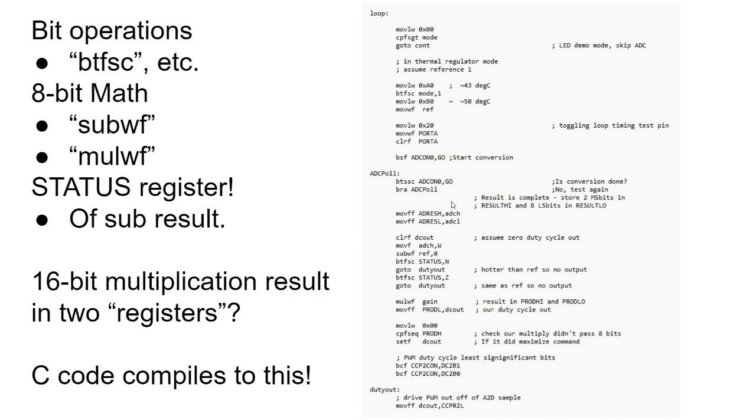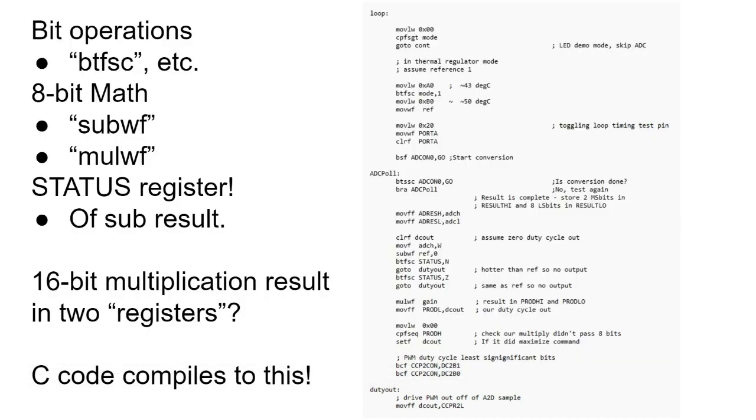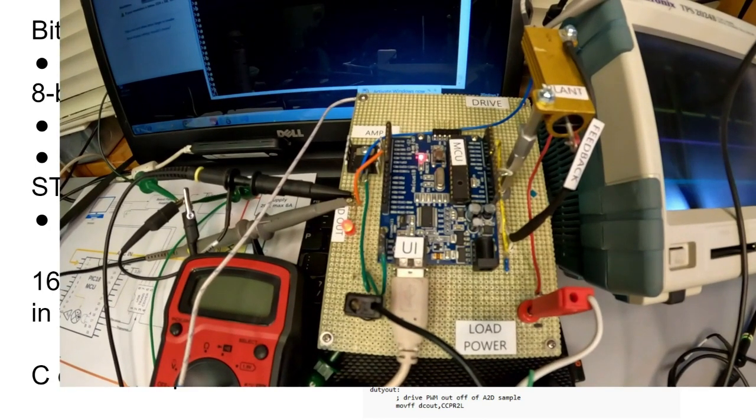And we're doing this, like I said, at 60 kilohertz. So when we observe our oscilloscope, we are modulating that, or moderating that, at 60,000 times a second. We're checking if we need to adjust that pulse width. Looking back on our video, if we confirm where we're at here, we close out our demo.